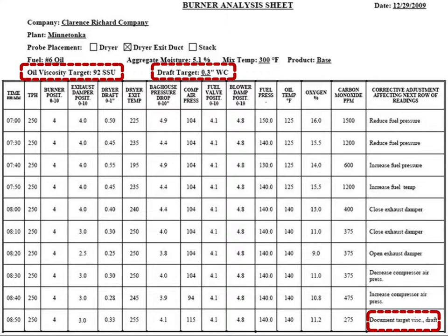will become less necessary. At the beginning of this, the CO, carbon monoxide, was so high that incomplete combustion of fuel oil was collecting on the bags. If this were LP or gas, the problems are the same, except the bags do not get oily and plugged. The O2, oxygen, was high as well.